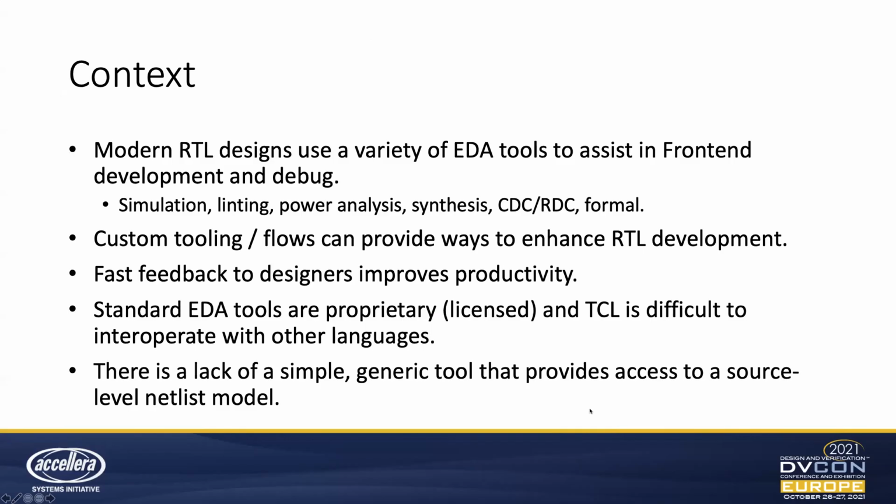So modern RTL designs use a variety of tools from a variety of vendors to assist in all aspects of development and debug. The tools fall into categories of simulation, linting, power analysis, synthesis, CDC, clock domain and reset domain crossing analysis, formal verification.